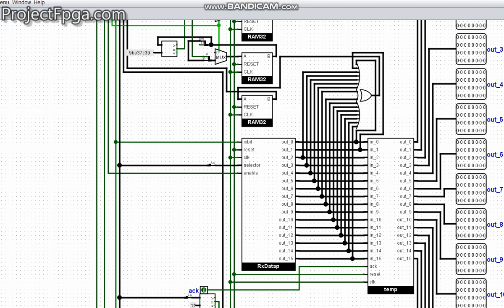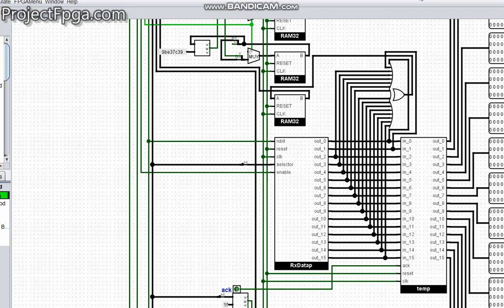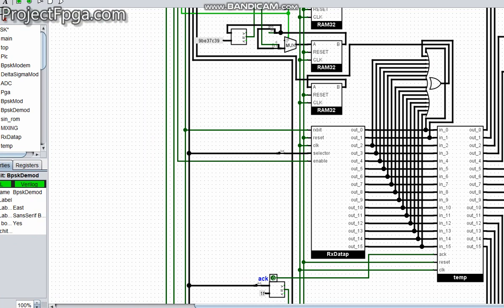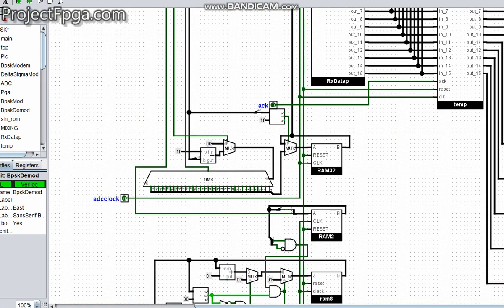This is what generates our checksum, remember, where all the inputs were XORed together. After XORing here, you get this checksum, and then you compare it with the actual checksum received. That is how this checksum serves as an error detector in the circuit.